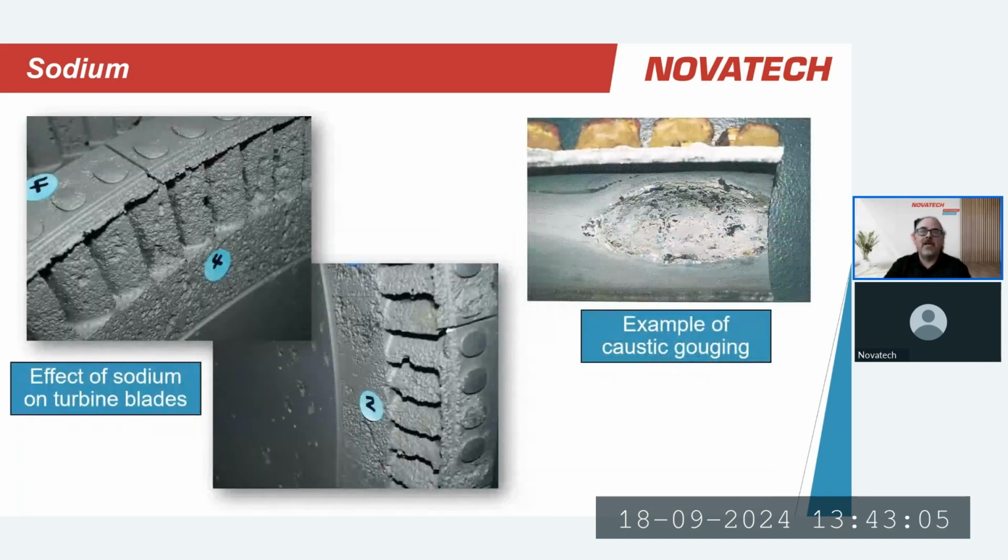You can see the impact of sodium. Sodium will lead to things like pitting and caustic gouging. If left unchecked, these things can be catastrophic. So it's not something to be taken lightly. It has to be looked at very closely.